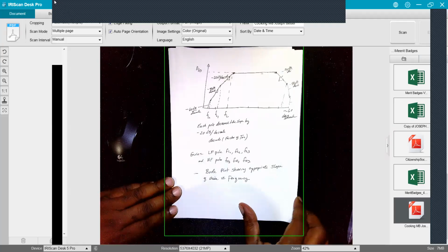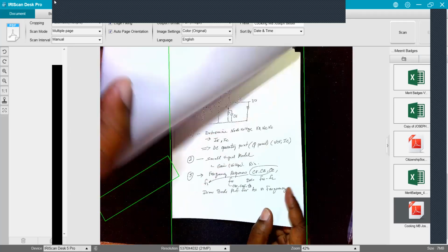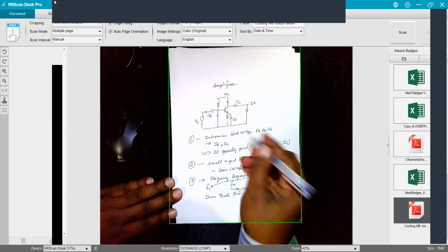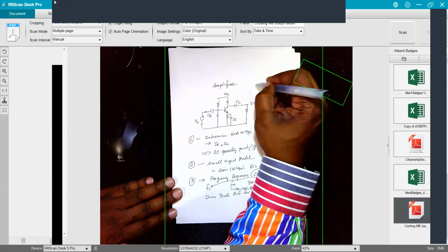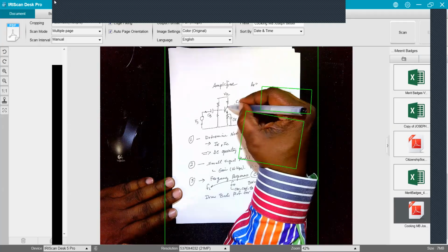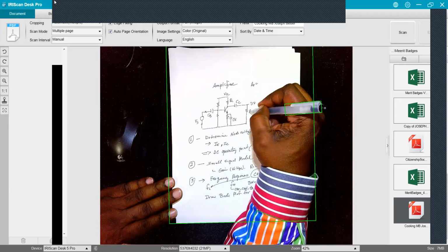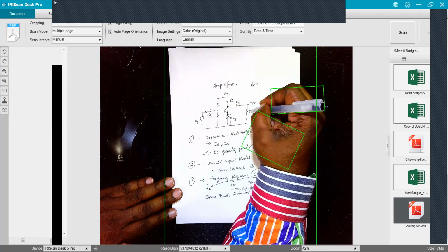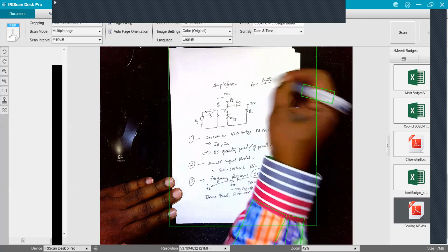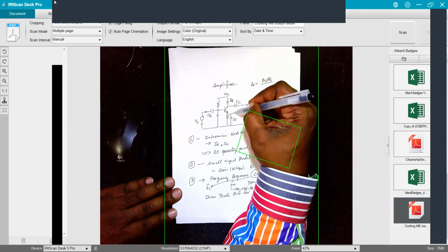Oh, and one other thing, I think I sort of mentioned it to you before. So we have our transistor here. Let's talk about our gain. Our gain of this circuit is approximately the impedance seen looking out of my collector, which is R sub C and my load R sub L, divided by the impedance looking into this node here.